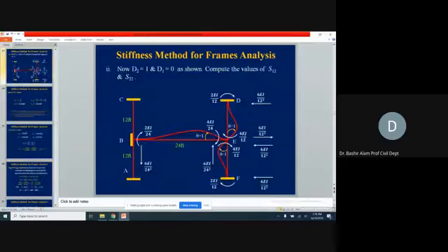And S21 is 2EI, and you can see it here in these decimals. Now, second column. Corresponding to D2, we now give our unit rotation. Here again, you can verify this clockwise rotation. Here you see the distorted shape, clockwise here and clockwise here also. At joint one, we need to now fix it. We are not allowing it anymore.